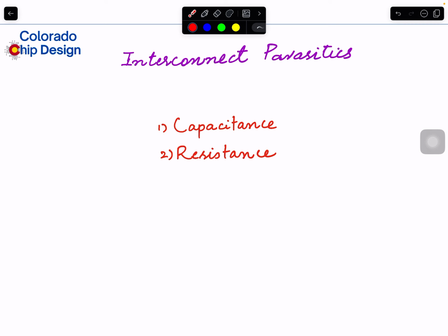But then we look into how transistors need to be connected to each other within a certain region, within a closer region, or within a larger region. So that's where I introduced metal layers, interconnects. And I gave an example of Intel 0.25 micron technology, which has five metals, and then vias.